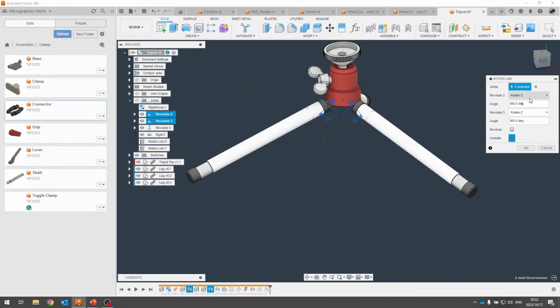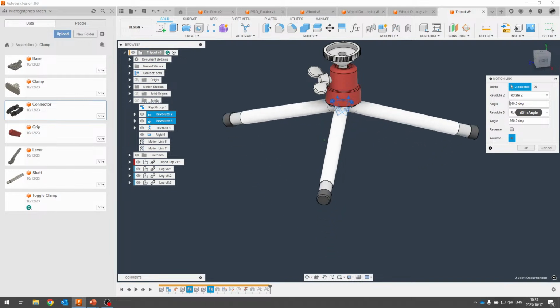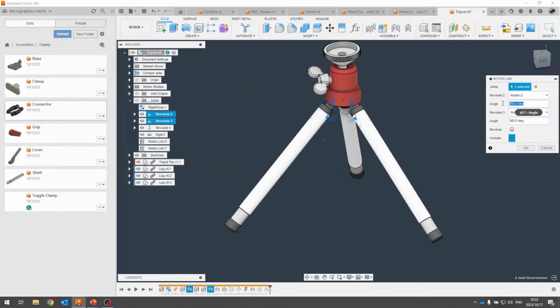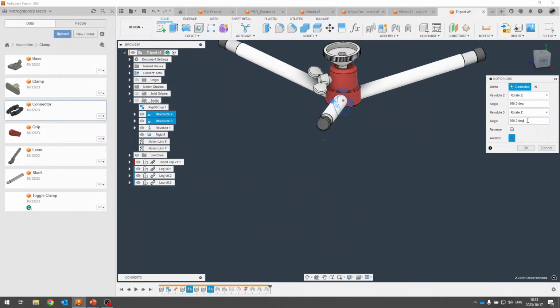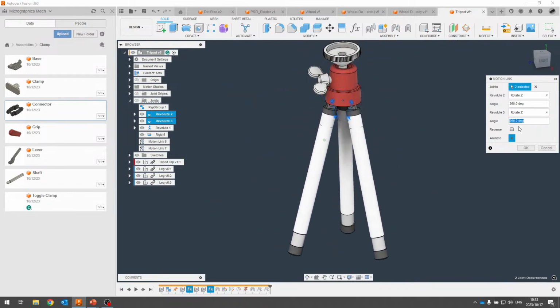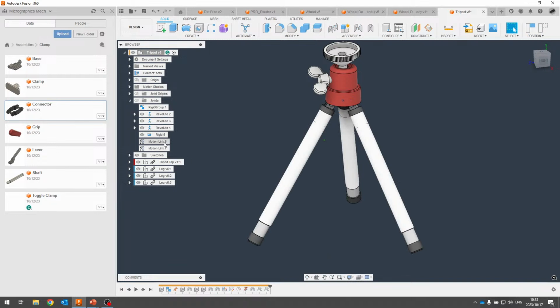And we can see here that it's 2 rotation joints that we chose, and we're able to set the relationship. If we change the angle of the first one by 360, the angle on the second must change by a specified amount. So we could actually say 180, and we'll see that when one of those move, the other one wouldn't move as much. And I think I've got an issue here with the, I'll just change the first one here rather.